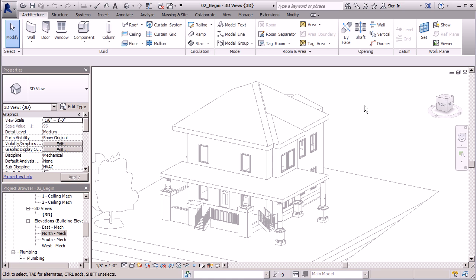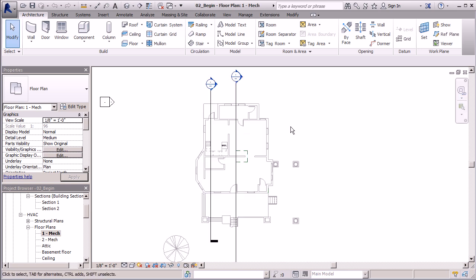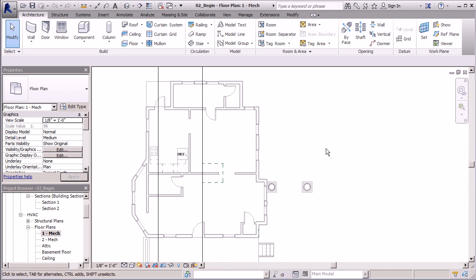So with that being said, let's go ahead and start separating our rooms into zones so that we can start designing our HVAC system. We'll start with the ground floor. The great thing about setting up zones and spaces and rooms is it makes it really organized when communicating to a mechanical engineer which room we're specifying that has issues with the HVAC. It also takes into account the area and the volume of each room so that we know the heating and cooling load requirements, which sets the pace for us to be able to start designing the system.